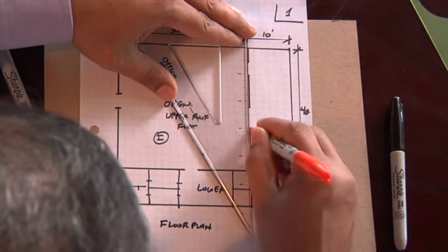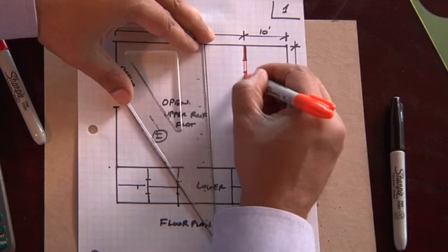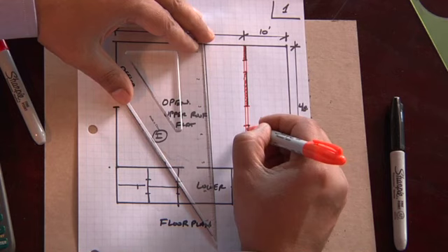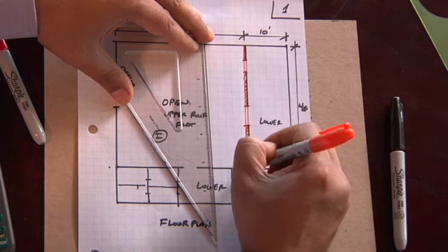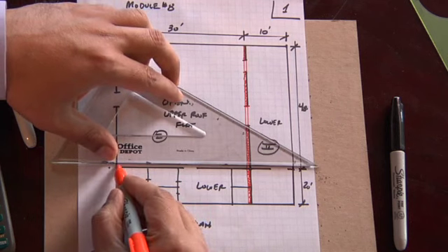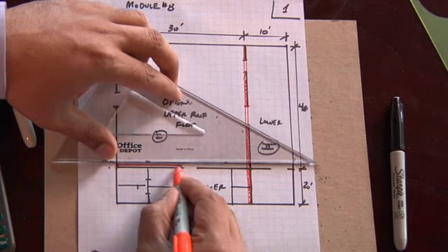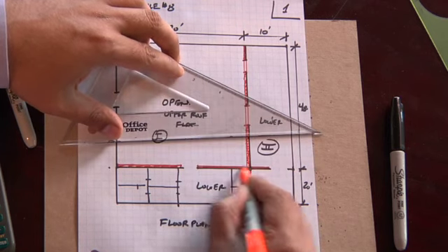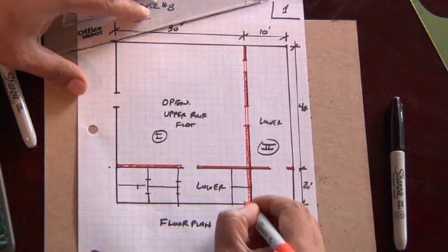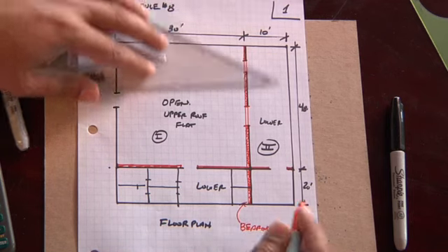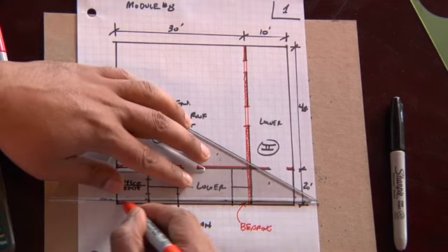And for simplicity's sake, I'm just going to draw it in here. Of course, we're going to leave openings in here, but we're going to make this our bearing wall. This will be an opening here, bearing wall. And we're going to make this a bearing wall because it's the most logical location given the way this floor plan is laid out. So now we have our designated bearing walls, and of course perimeter walls are all bearing walls in this case.